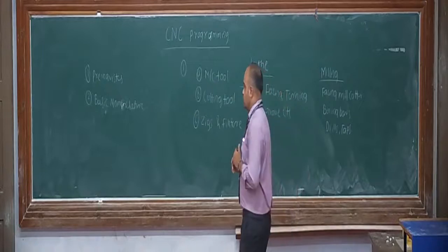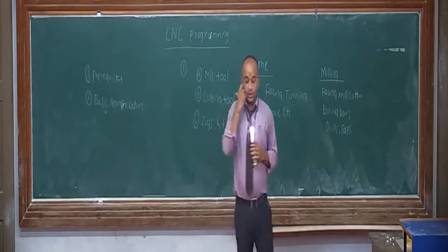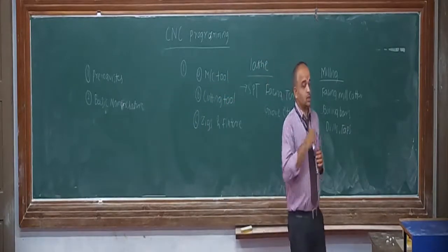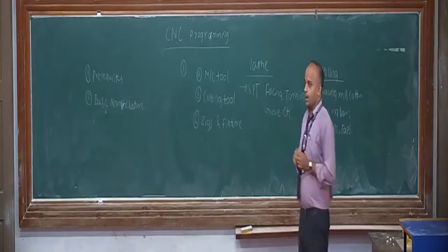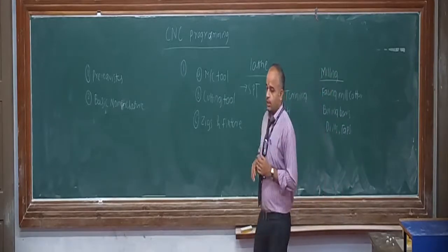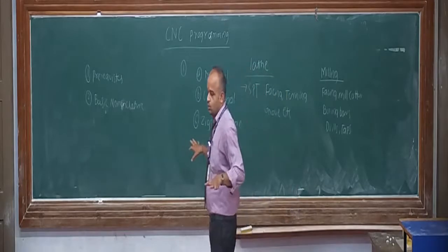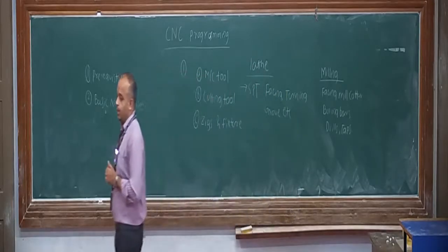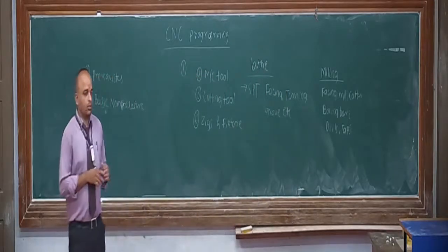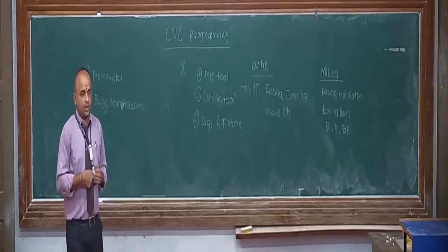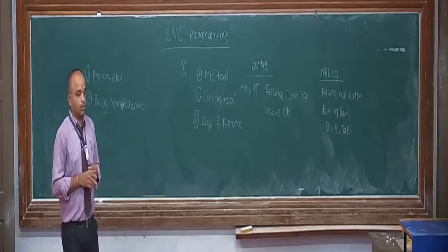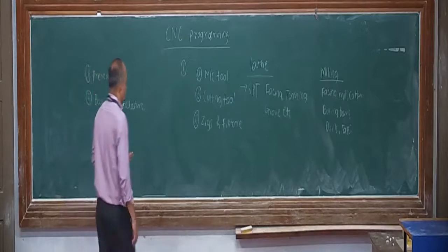Also, a hydraulic fixture requires a certain kind of maintenance. If during the operations the hydraulic pressure is lost, it might happen that the workpiece is loosened during operation itself, and accidents have happened. But that is not the case with a manual fixture, because you have already tightened it, so there is no possibility of the product getting loosened. So this is nothing but the fixture.